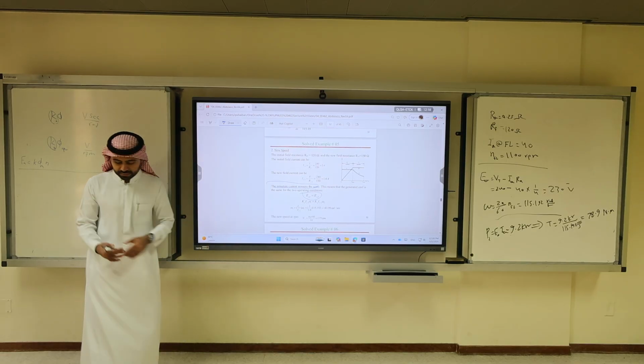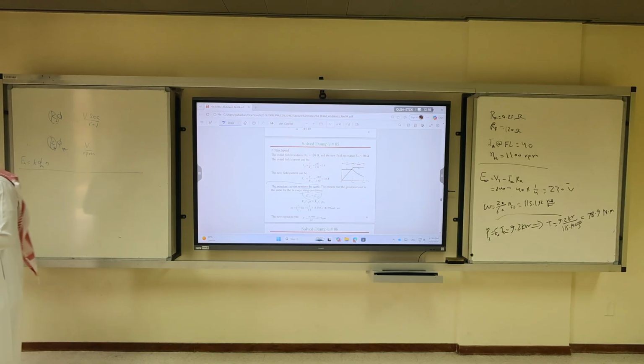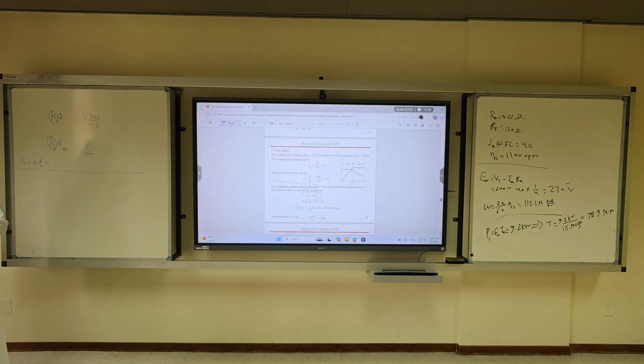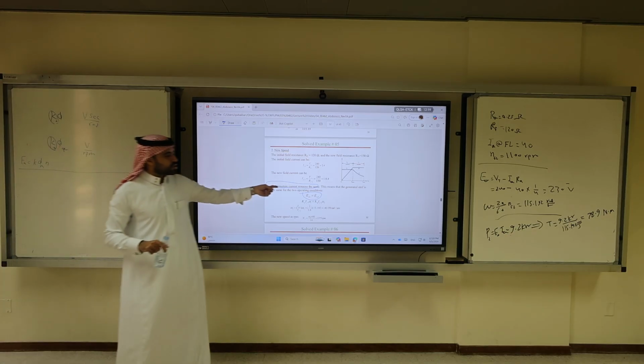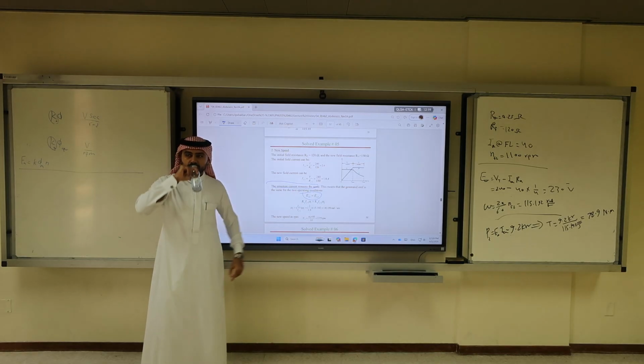Doctor, the torque will be lower, correct? No, the torque will be the same. The same. So we overall will have... No, the torque will be lower because EA times IA is fixed. So omega is up, torque will be lower. You're right. So we are not increasing the amount of power that much. No. That's the purpose of this assumption. The drawn current is fixed.